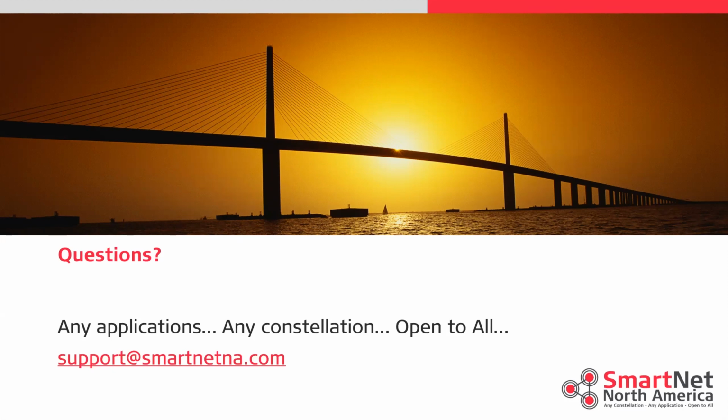There are small changes afoot, 5 millimeters to 5 centimeters, for this broadcast coordinate update in the US and Canada. In 2022 is the NATRF update for NGS in the US. That's a 2-meter update. That is not what we're talking about here. We're only talking about today the adoption of a new realization and small changes to the broadcast coordinates.